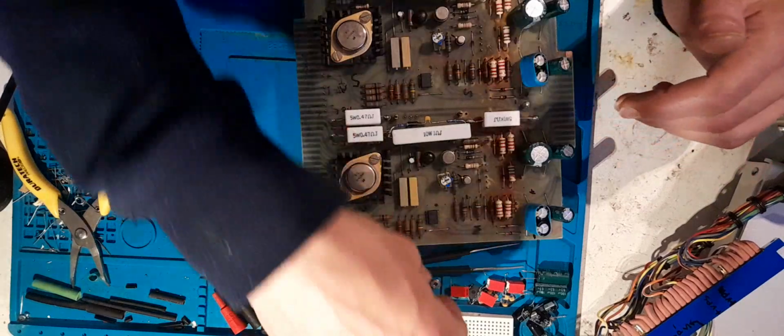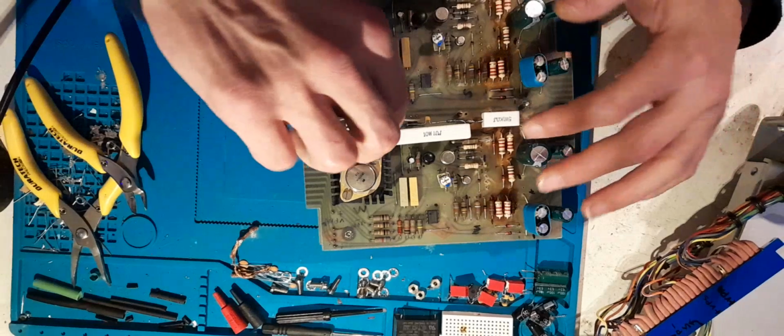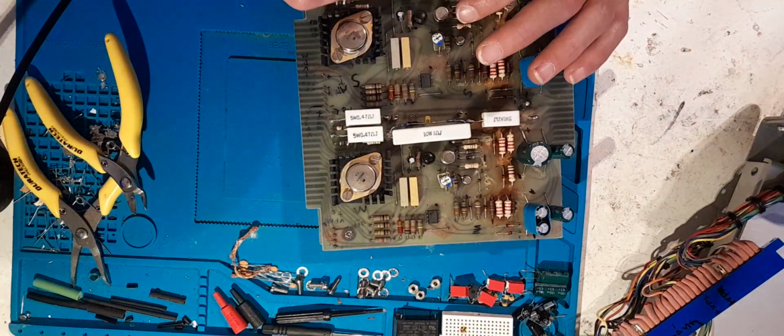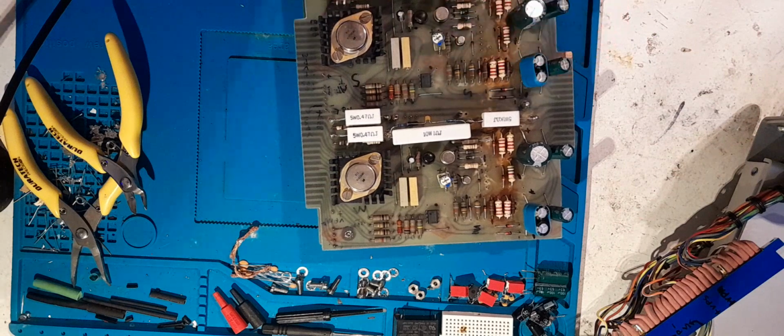And we'll play around with capacitor values until they get up to the point that I don't want to go any bigger, and then leave them there, and then we'll go and start compensating the opamps. We'll probably come back to the references later and see, after the opamps are compensated and not oscillating, if the references still need such big capacitance values.